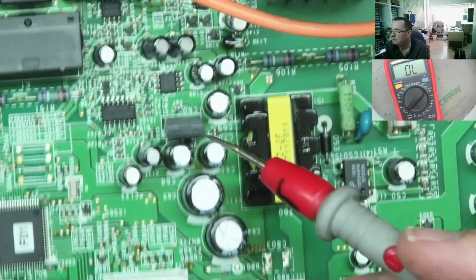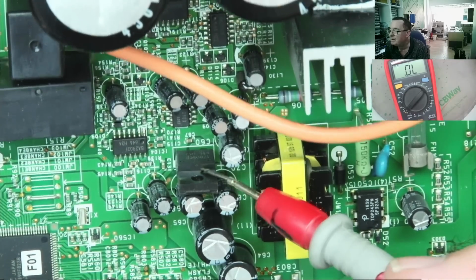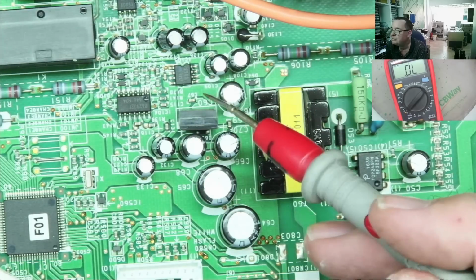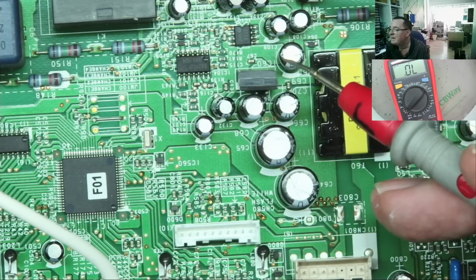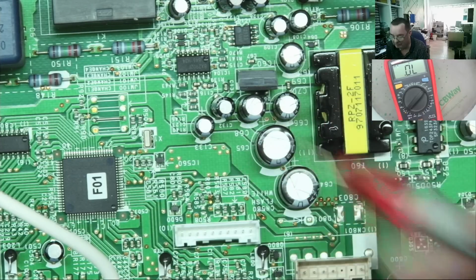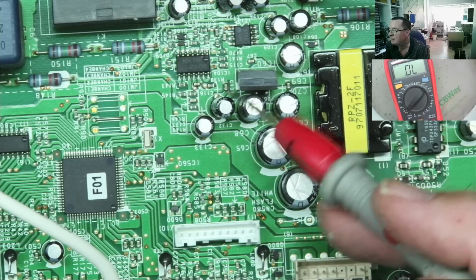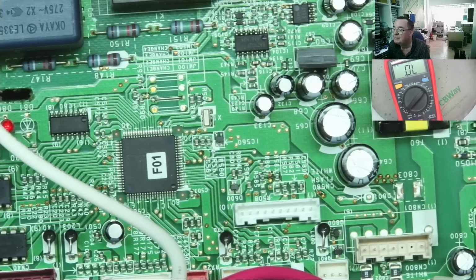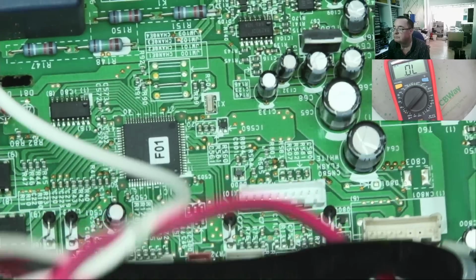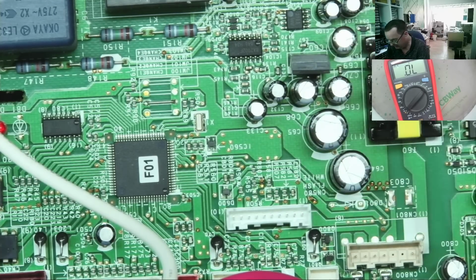Looks like a voltage regulator or something. Yeah, another 7805 on the output. So this is another 5-volt supply, and this will supply some of the chips in this area. So we could power this board up again, like we did with the other one, and just figure out if we have supply here. That's another good step. If we do have supply into this area, 5 volts, then we can look for this EEPROM.